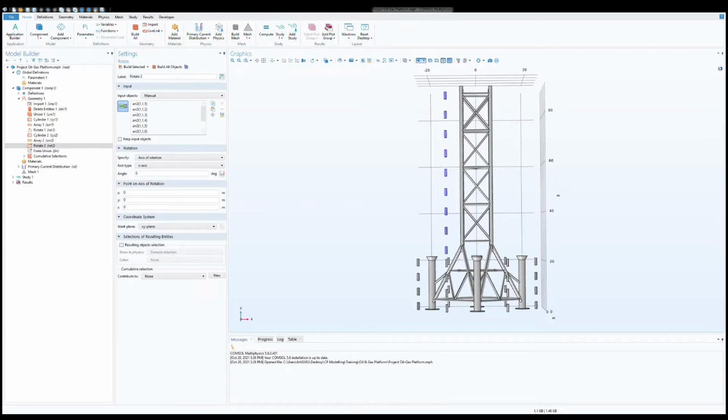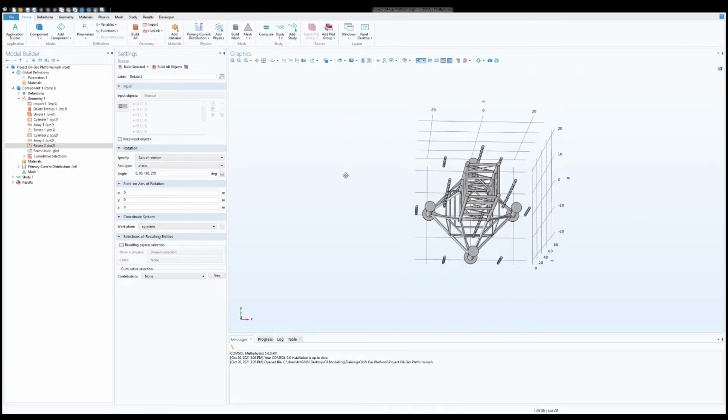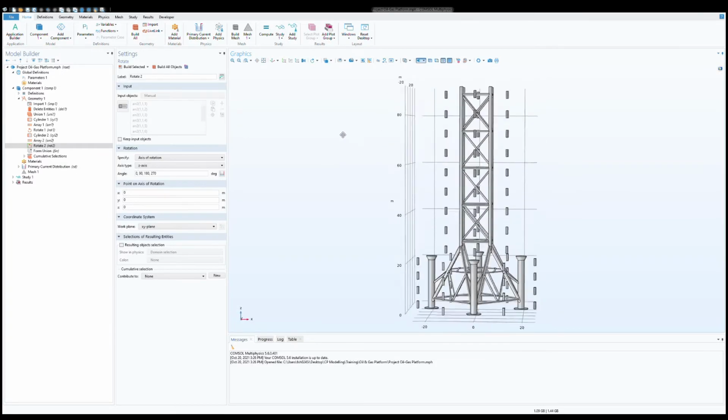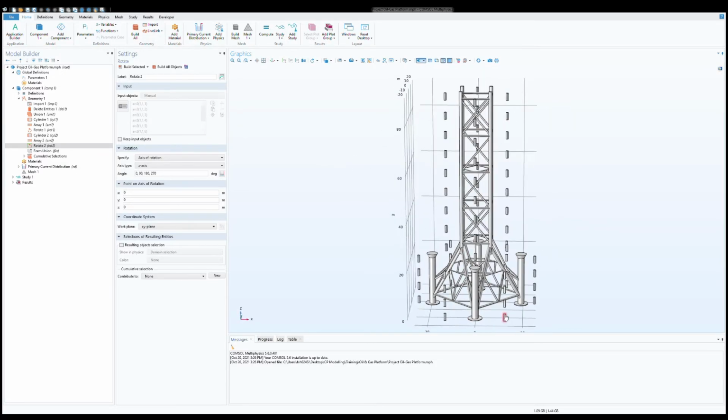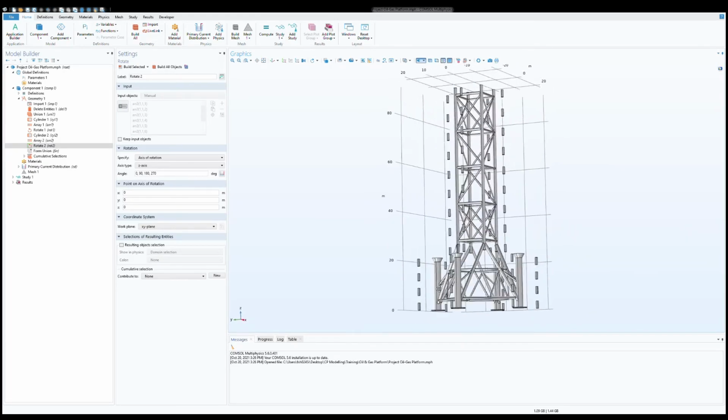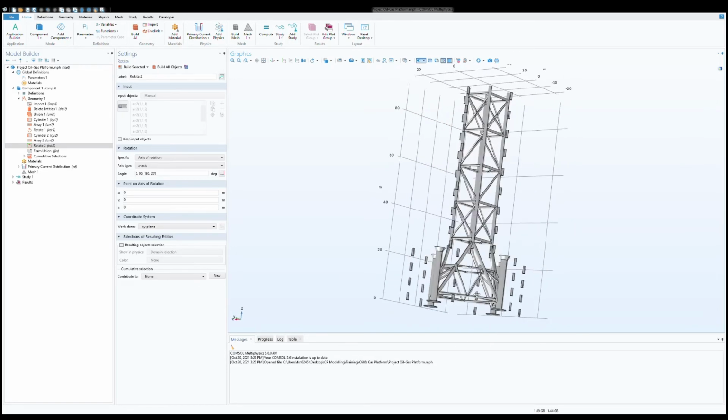Now select all the anodes to be rotated, and for the upper part we are keeping them 90 degrees apart. It is because we have less surface area to cover for the upper part. You can see here 4 arrays of the anode along the upper part of the platform and 6 arrays of the anode we are going to use for the lower part of the platform.